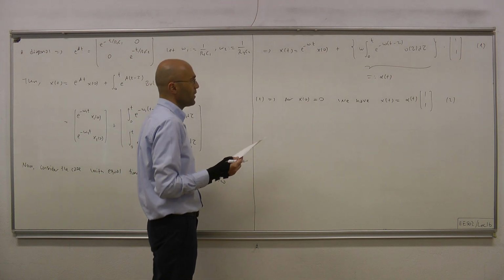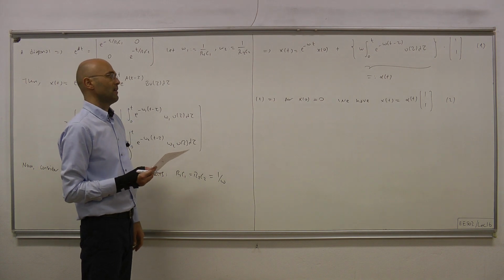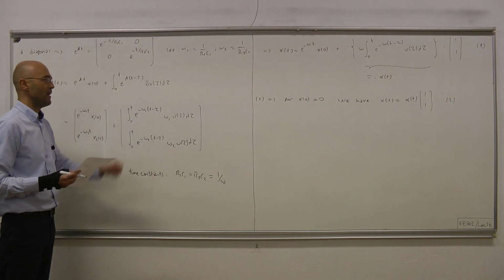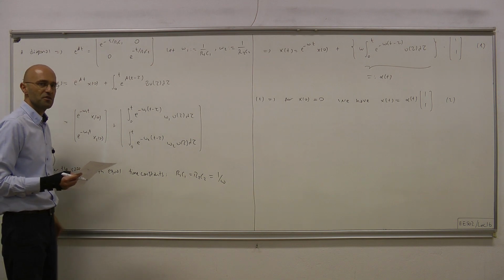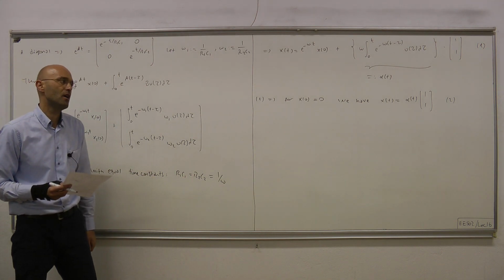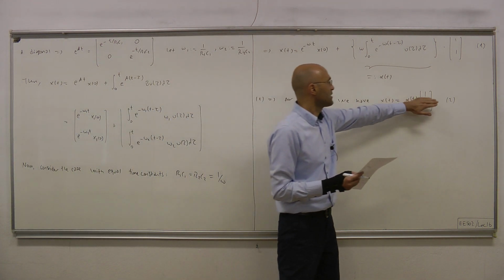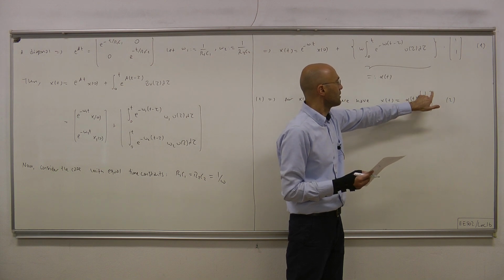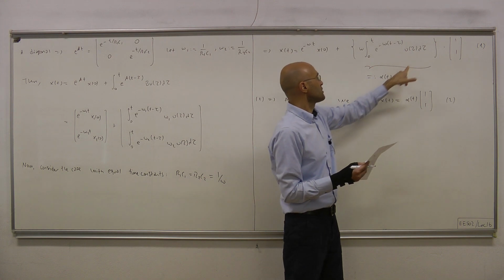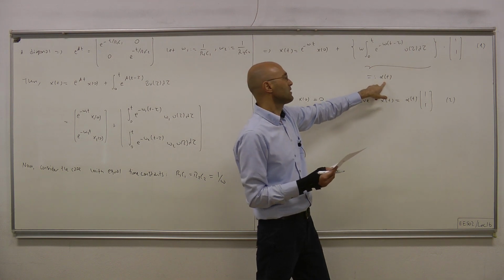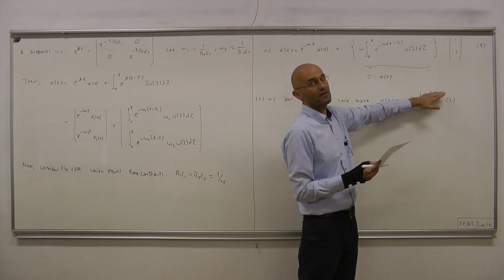Okay. So what does this equation 2 imply? Let's figure out. And that equation 2, we reached under the assumption that the time constants are equal. Okay, R1C1 equals R2C2. Now 2 says that, let's consider only the first capacitor voltage, by choosing u of t, suppose that we can make alpha t whatever we want. So that means we can make the first capacitor voltage whatever we want, okay?